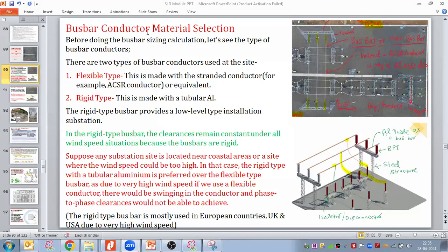Okay. Yes, sir. The same thing the client also told me. Once I asked them why you are using PT, we could have used CVT here. They told me that the precision in PT is higher than CVT. Yes, so there is no harm in that. It can be used. If the client agrees to pay the higher cost, as a contractor, what is the problem for that? It's okay.